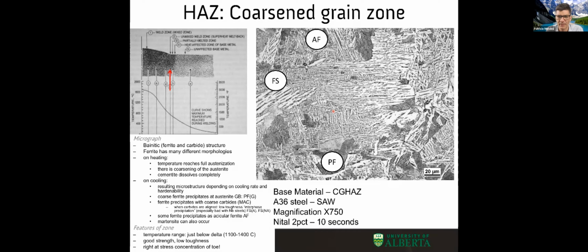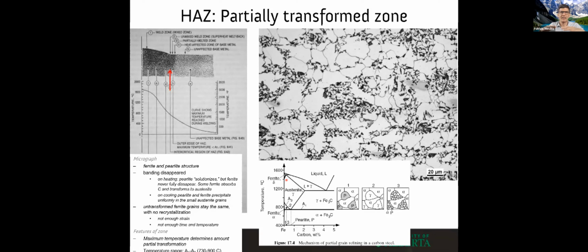Grains are high energy features. So if we give heat, it's going to accelerate at high temperatures, we accelerate the diffusion, and we have fewer grain boundaries. How do we have fewer grain boundaries? Bigger and bigger and bigger grains.